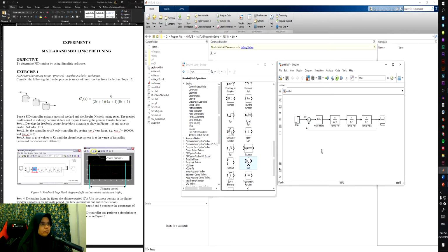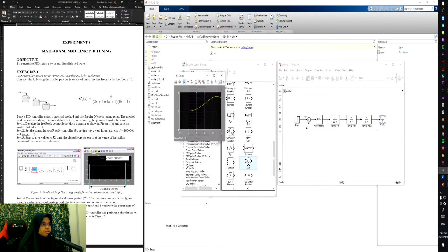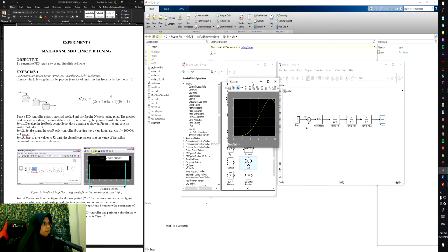So when we also want to compare, we can hit the run button, but don't run away. At the first place, get kind of graph. When we see here, it means the simulation time from 0 to 10 is not enough. That's why you have to increase this one.